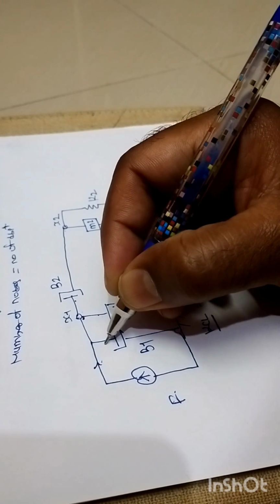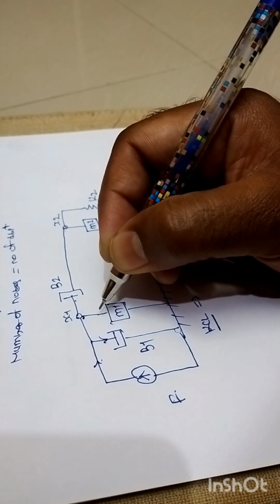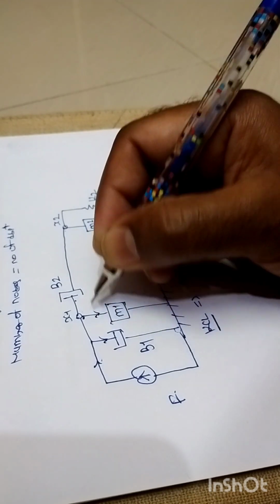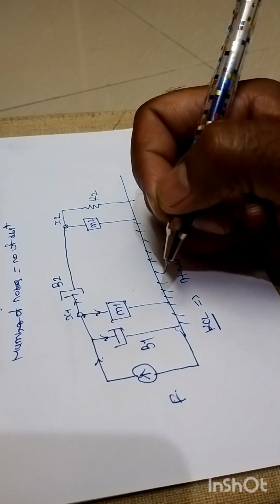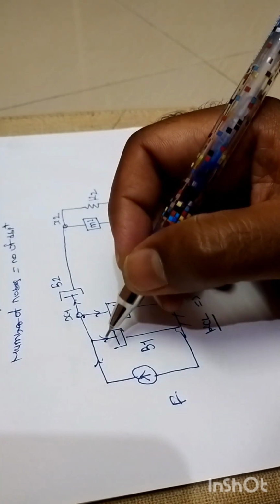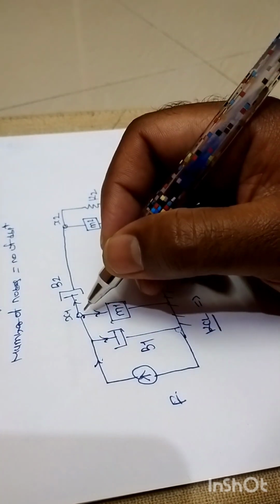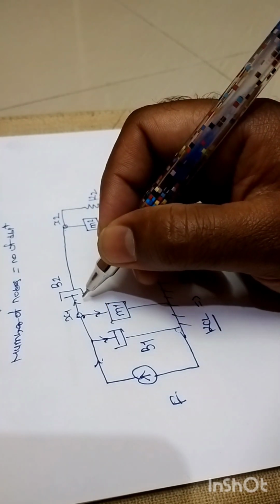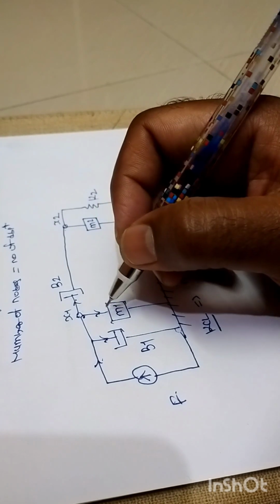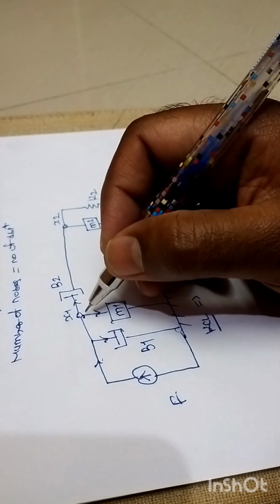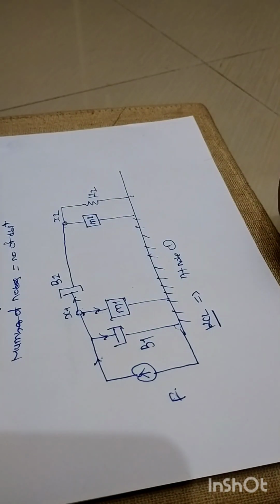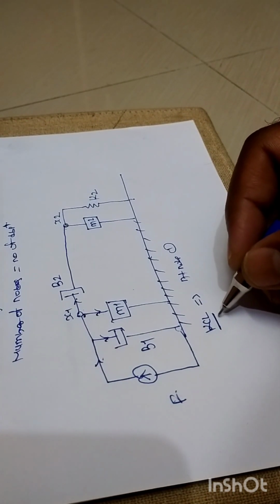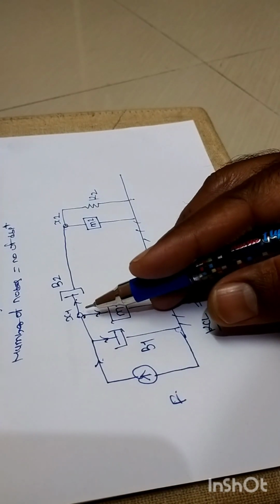So we need to assume the direction of forces belonging to these remaining 3 branches. This will be the first one, this will be the second, and this will be the third, right? So the direction of applied force is incoming to this node. So obviously as far as these 3 branches are concerned, the direction of force is outgoing from this node, right? So by taking into account this fact, when we apply this Kirchhoff current law strategy in terms of force